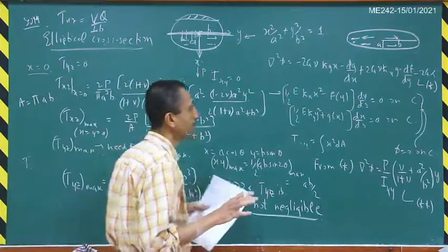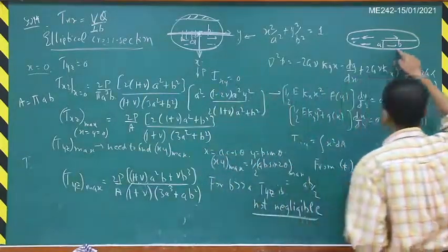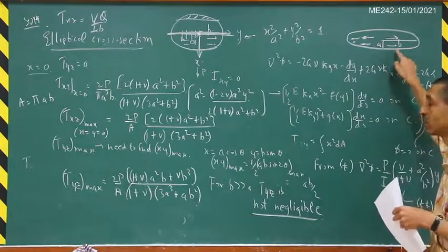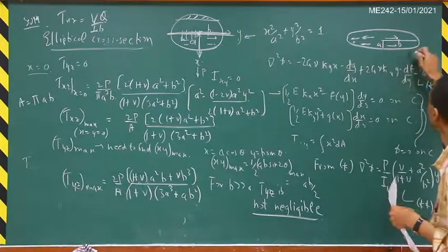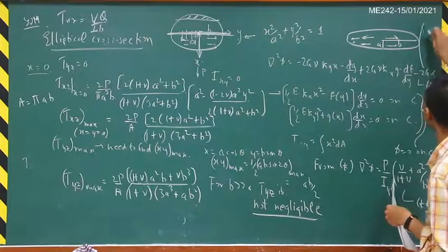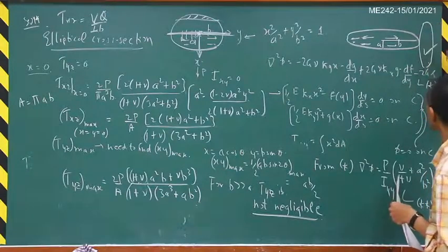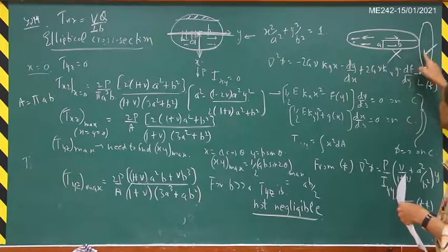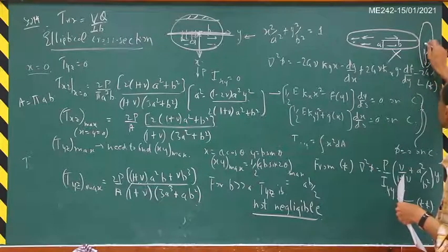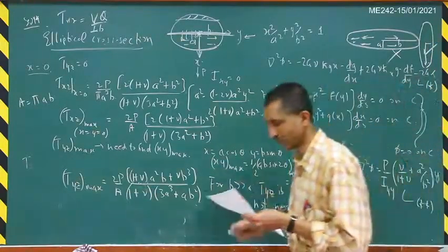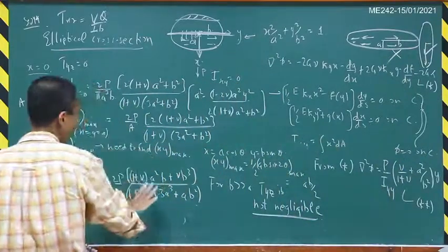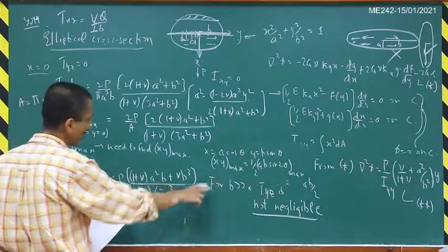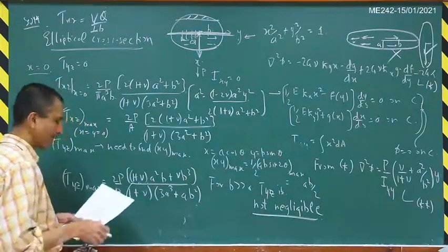So basically, to summarize, if you have this particular case and you use your strength of material solution, then you can get very large errors, right? So you have to be very careful. Suppose your cross section is of this particular kind, like this. Then here it is okay, here it is not okay. So for this case you are okay to use the strength of materials solution. That is the reason I wrote all these expressions, so that you can see that for b much greater than a, tau yz is not a negligible quantity.